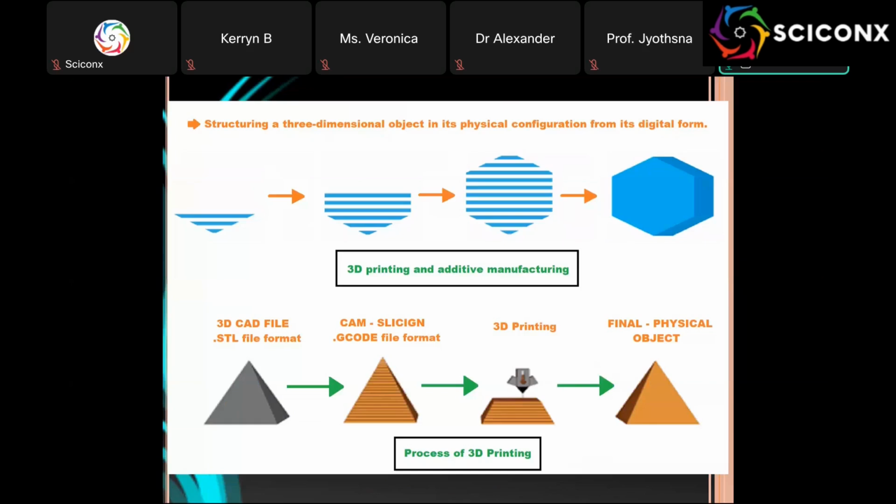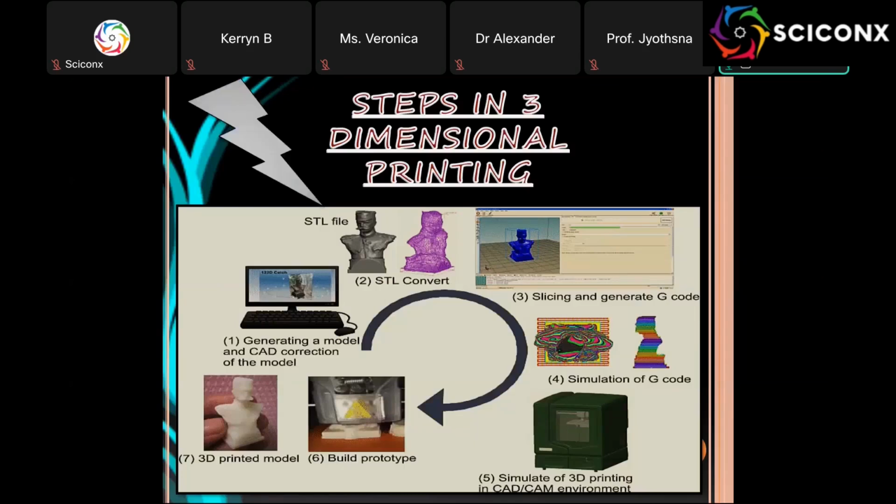In the third step, the finishing is done when the model or replica which was produced becomes oversized, or there may be some kind of surface roughness present. Therefore, layer by layer, extra material has to be removed for an accurate fitting. These are the steps of three-dimensional printing that will be followed through the modeling process, the printing process, and the finishing.